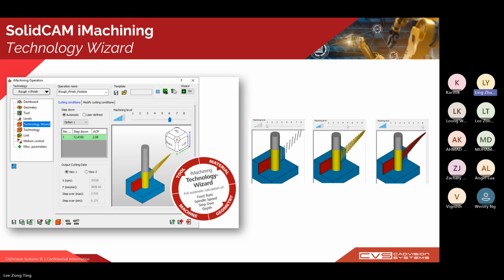This is ideal if you have a very old machine, or maybe a less rigid setup, or delicate tooling that you wish to protect. And level 8 basically pushes the envelope with maximum material removal rate. This means that the cycle time is less. You're removing material at a relatively largest amount and it is high performance. Levels 2 to 7 offer smooth, graduated steps in between, letting you fine-tune based on real-world experience.